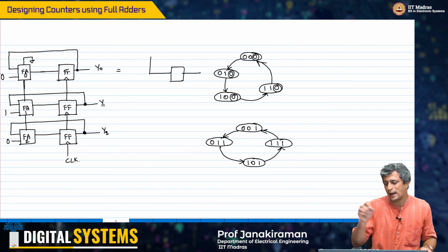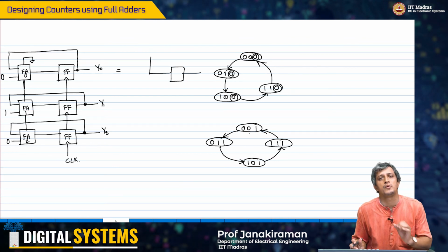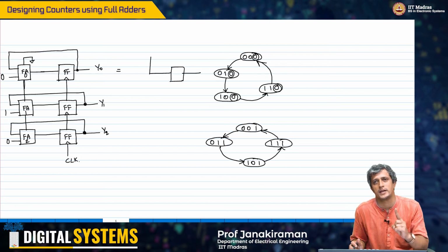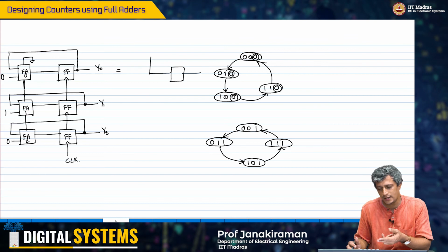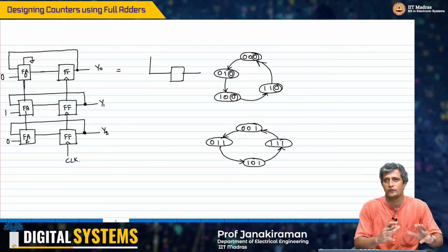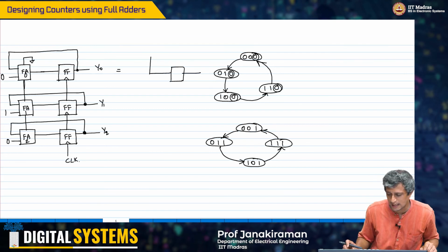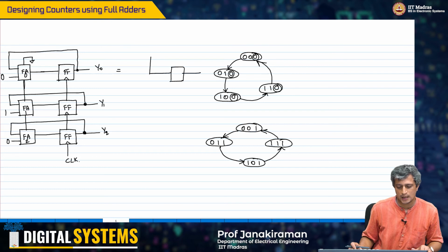So it's going to go back in circles like this. Of course, the first bit will simply be fixed to 1. You don't have to do anything. You are still doing just 2-bit counting, and therefore only for the Y1 and Y0 you have to figure out the logic diagram appropriately and get this to work accordingly, right?